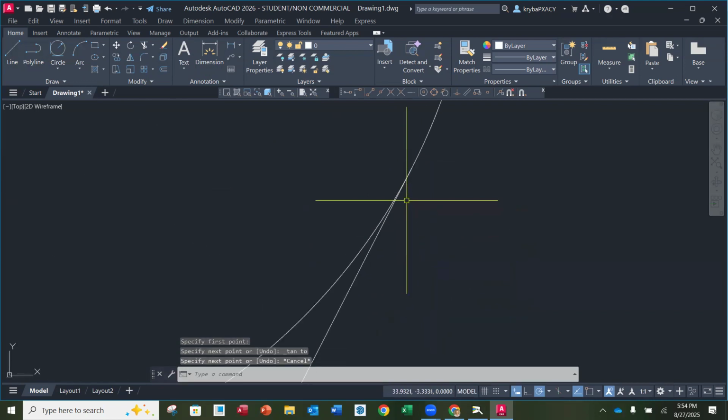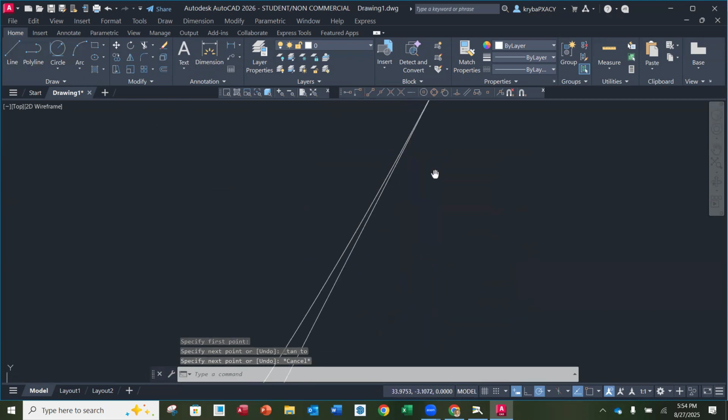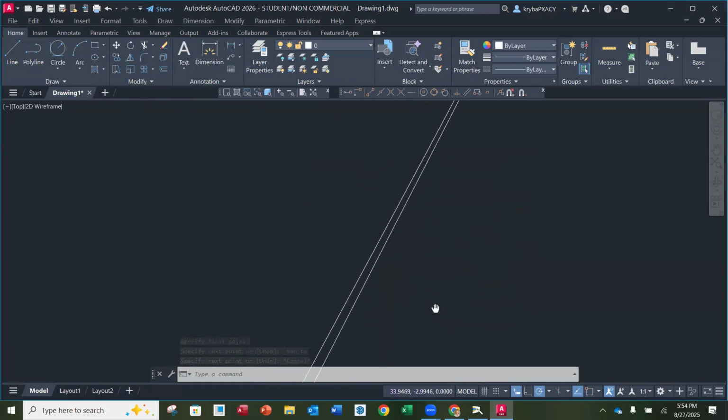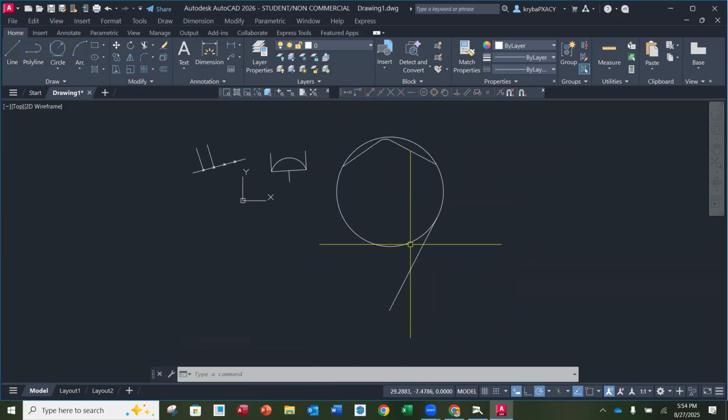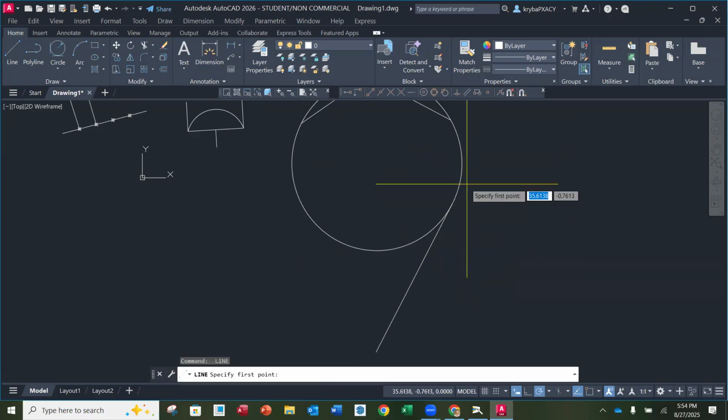And now when I zoom in, and again, these are things I'm going to be doing when I look at your work, I'm going to see, is it coming together? It is, and it's not overlapping, then I know you used your object snaps. And again, really important, especially when these files are being used downstream for other applications, so that there's no errors and such. We did tangent, radius.